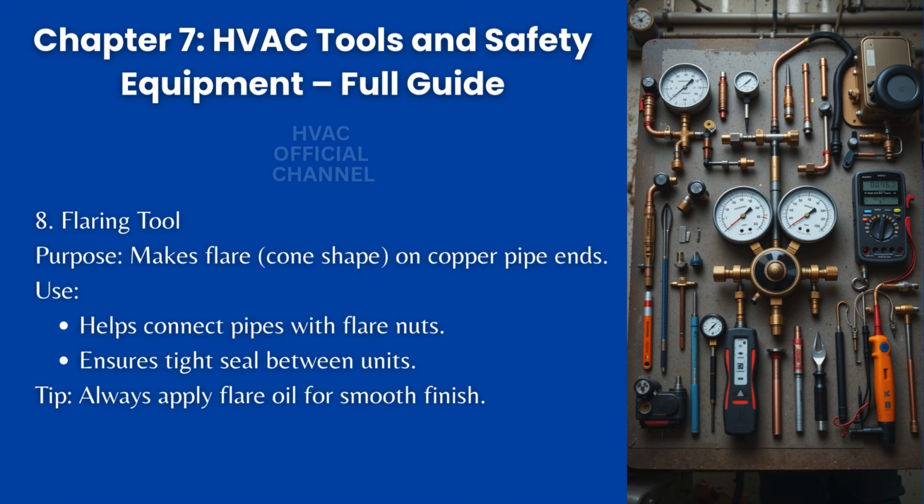8. Flaring tool. Purpose: makes flare, cone shape, on copper pipe ends. Use: helps connect pipes with flare nuts. Ensures tight seal between units. Tip: always apply flare oil for smooth finish.